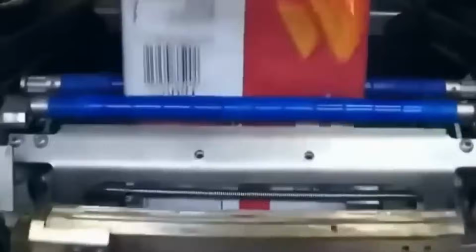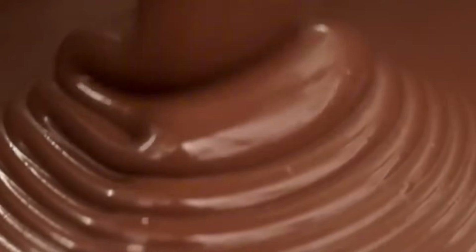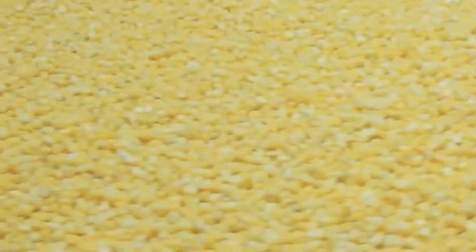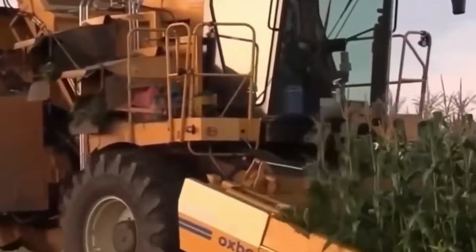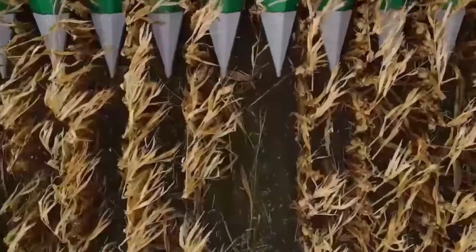A changeover process is executed based on preloaded digital recipes that configure roller settings, fryer dwell times, seasoning flow rates, and packaging parameters. Downtime for changeovers is minimized using quick-release parts and automated washdown stations. Production lines are modular and scalable. A high-capacity Doritos line can produce between 3 and 7 tons of finished chips per hour, depending on product format.